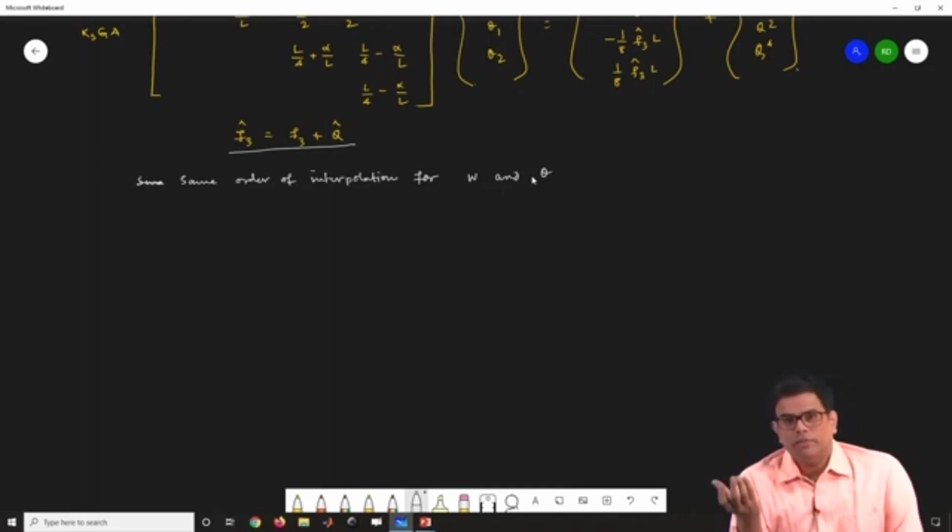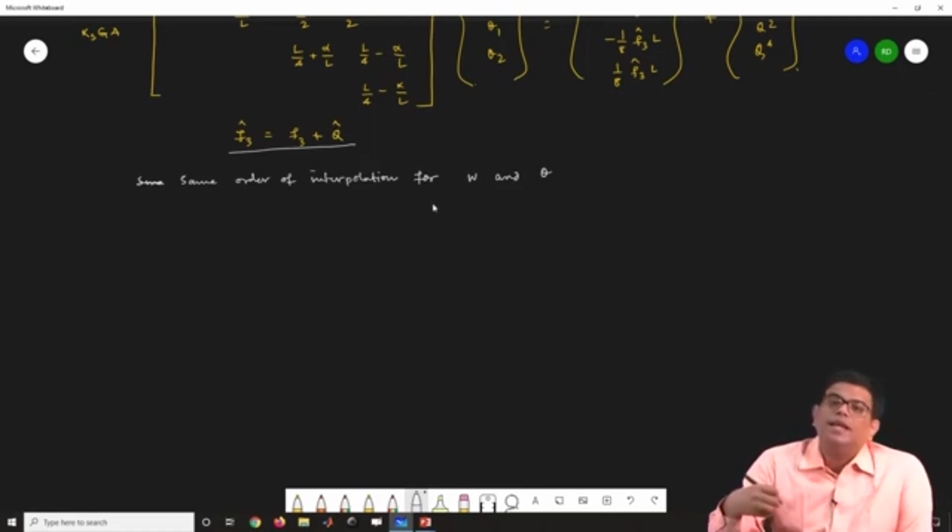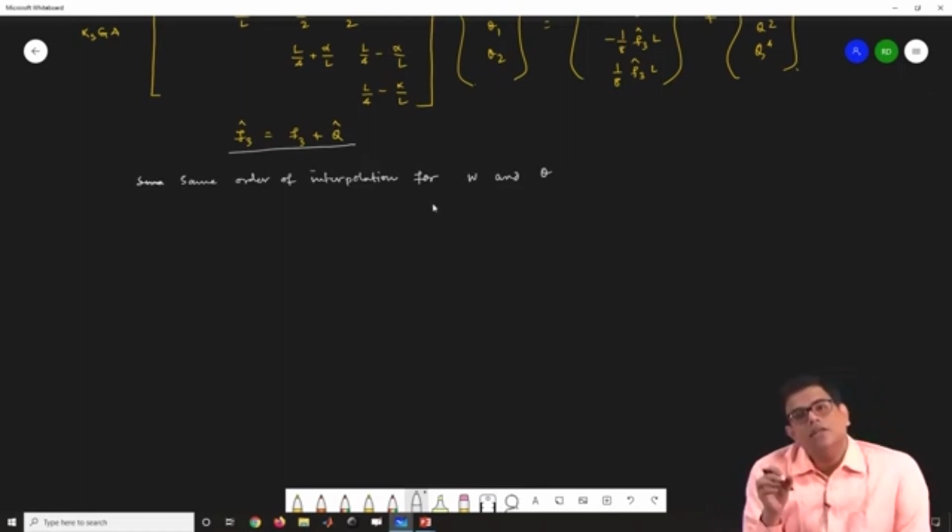The main problem is that our bending energy becomes 0, because at the thin beam limit, d theta dx has to be 0, because theta becomes constant. Now this is a numerical issue that we can alleviate.